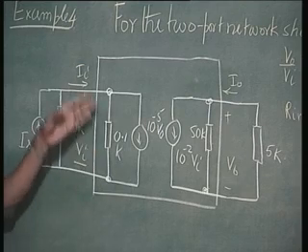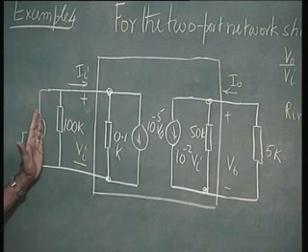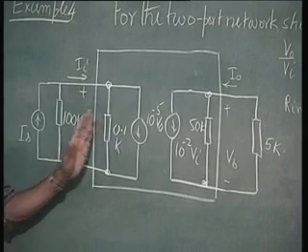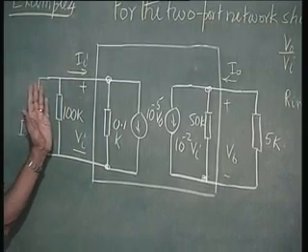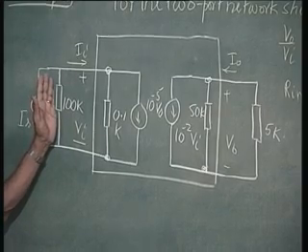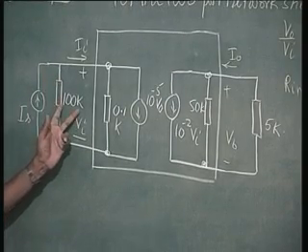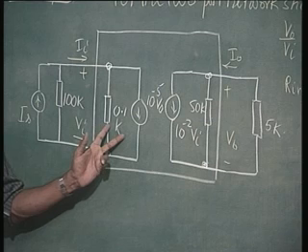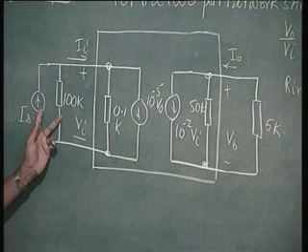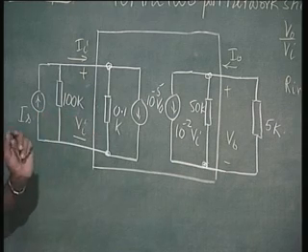Let us consider this. Here we have a current source feeding on to the input. Whether it can be represented as a current source or otherwise is justified by comparing the impedances. This is 100K and this is 0.1K. So this is definitely a current source drive. There is no doubt about it. The source impedance is very high compared to what it is seeing.